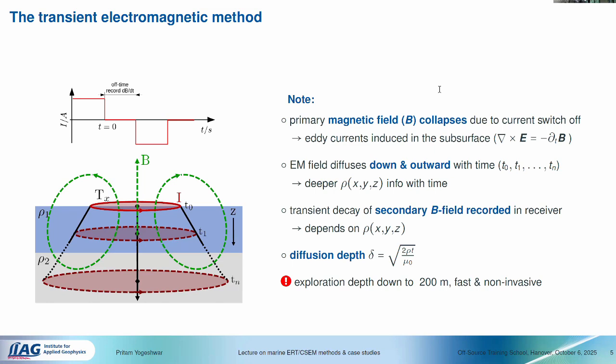It doesn't help you much. Then you can do stacking, but if you stack 10,000 times, you have an increase of signal to noise of a factor 100, which is good. That's 2 decades in magnitude. But then if you want another decade in magnitude, you need 10 times 10,000, too much. No? So at this point, you're basically lost using such a setup.